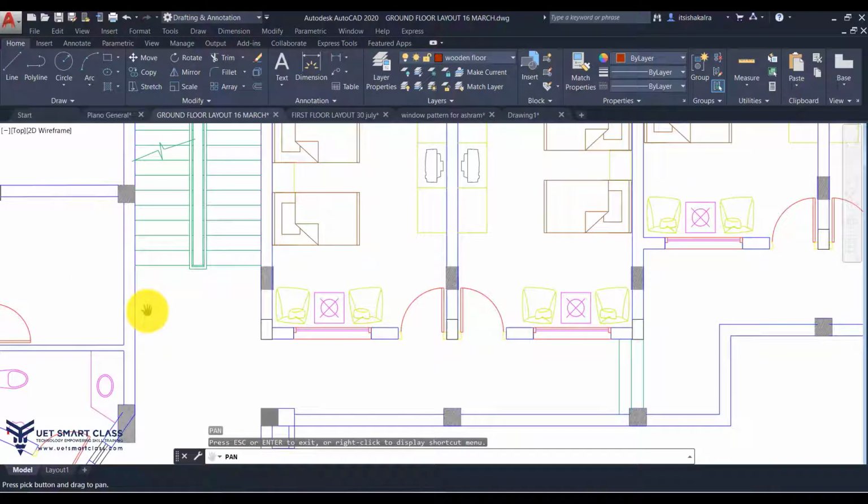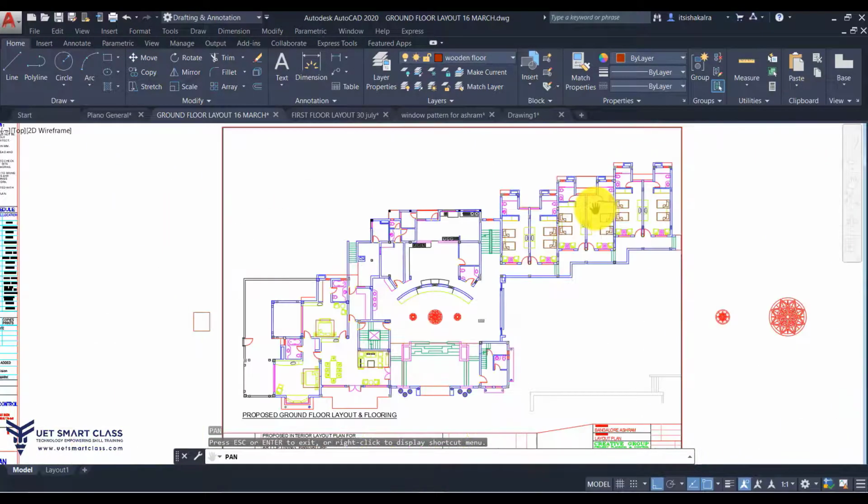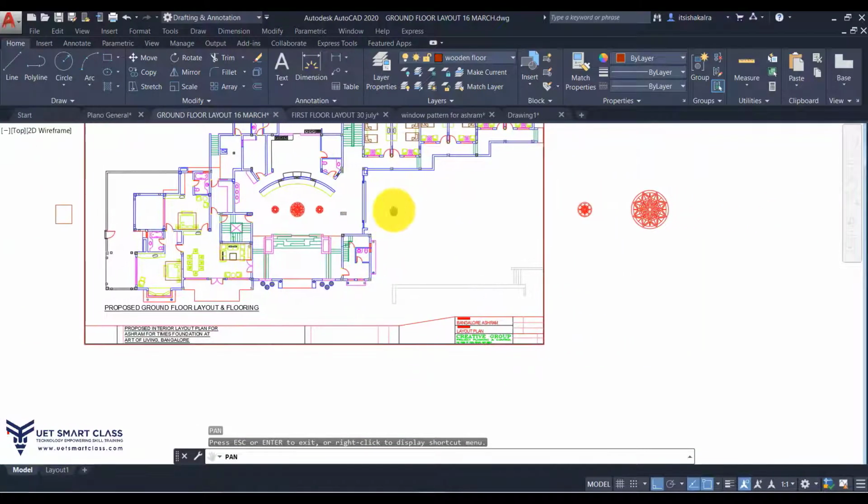You can create a CAD library of your own, wherein you can save all the blocks and important drawings, like in architecture, samples of beds, common standard sizes of beds, side tables, sofa sets. Whenever you require, you just have to pick and draw, like from the design center.